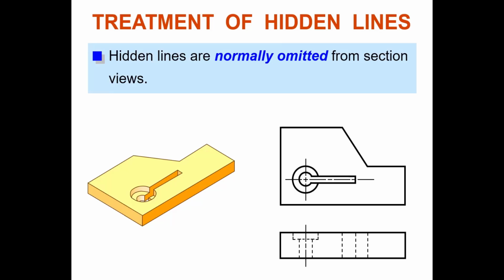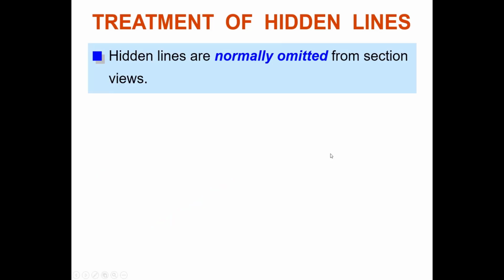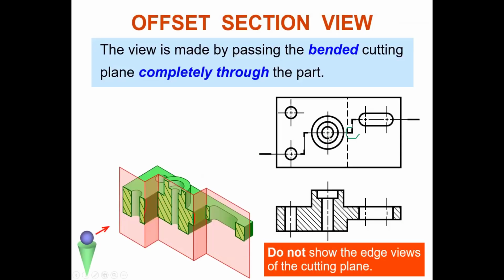In the front view, I want to make a section view. At the plan view, I make a cutting plane. Is it full section or offset section? The answer is full. How much do we offset? Offset is like what we did just now, guys. This is offset, understand? Because we want to cut, we want to see the drill through, we want to see the internal structure of the C-bore,